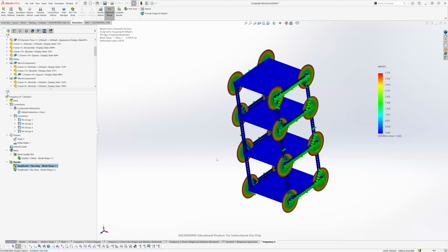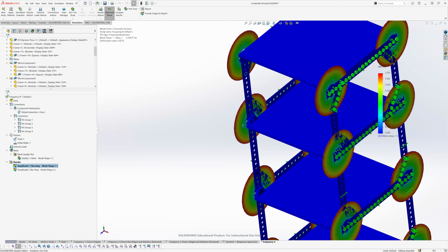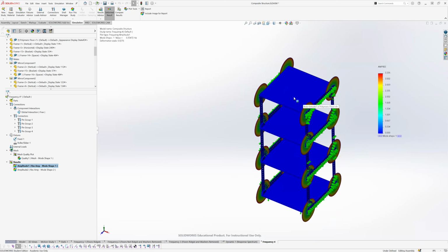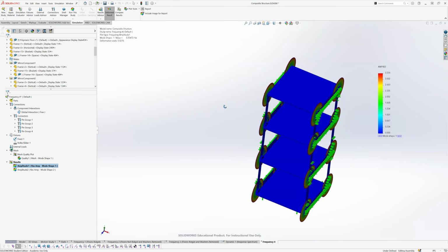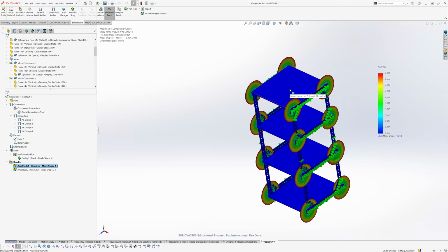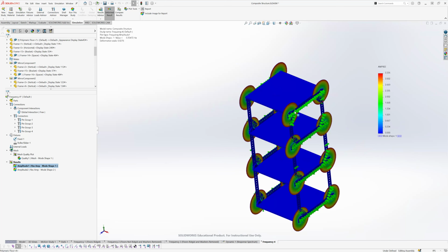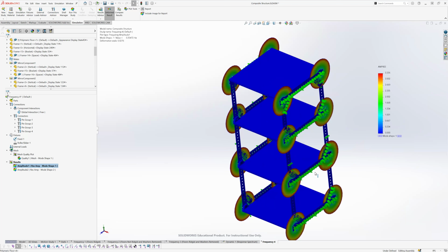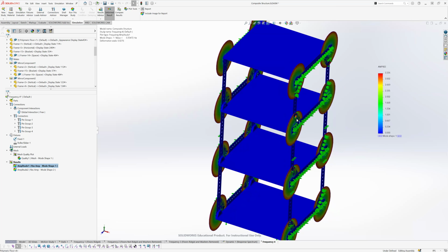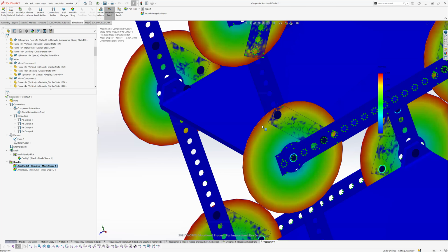Another thing here, obviously, this is the issue I was talking about earlier, with the washers doing this really, really weird type of behavior. I honestly don't know why these are behaving this way. This is why what I actually ended up doing was going back and making all the washers rigid bodies, just to avoid this kind of unwanted effect. So that's what it looks like.